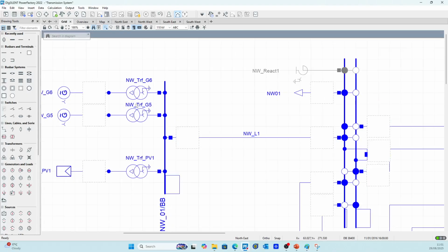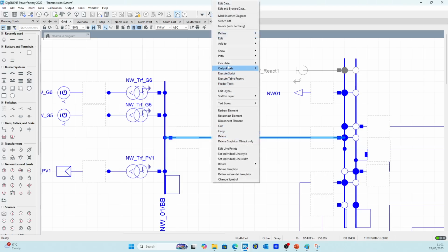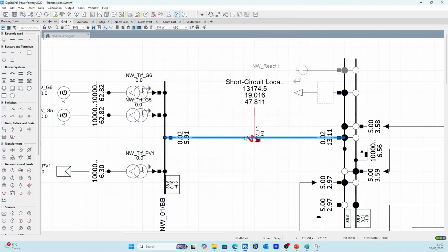Well, normally we have to measure the current entering into the transformer and leaving the transformer. For example, if we have a fault in here, we need to measure the CT in here and the CT in here. Since the fault is outside the box of the transformer, the relay should remain stable. But if the fault is within the transformer, we expect the relay to trip.